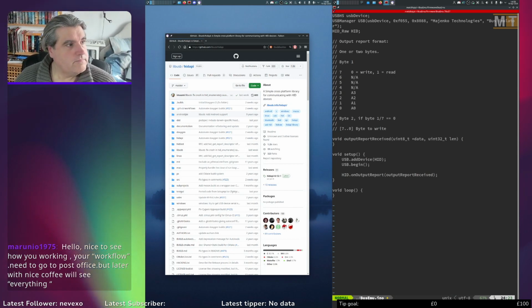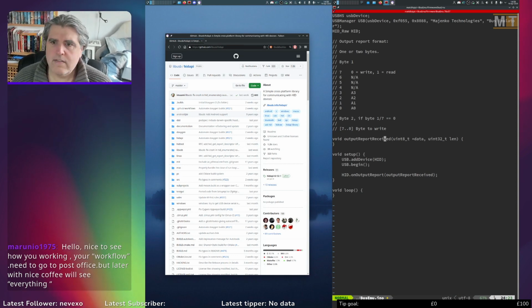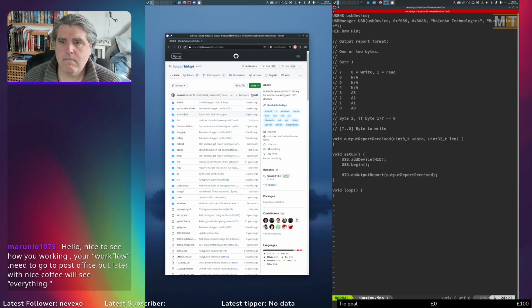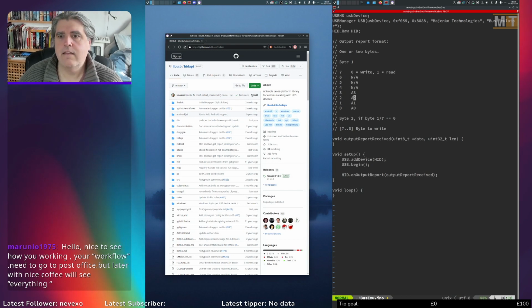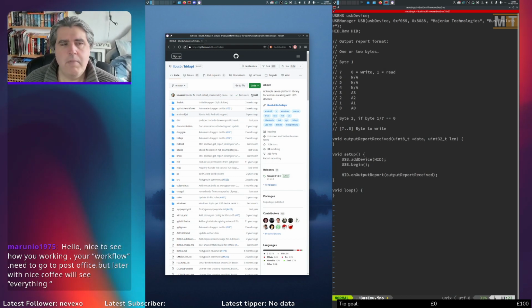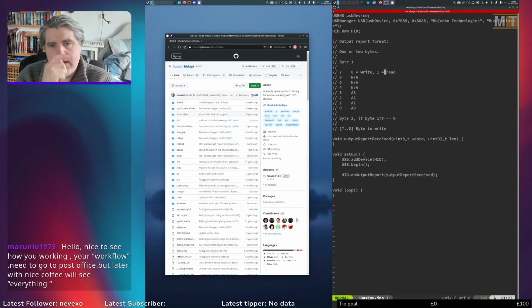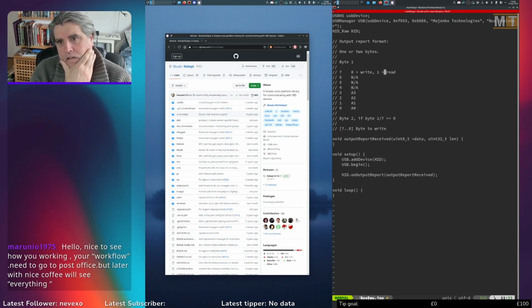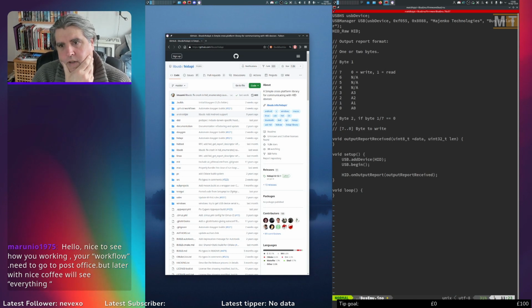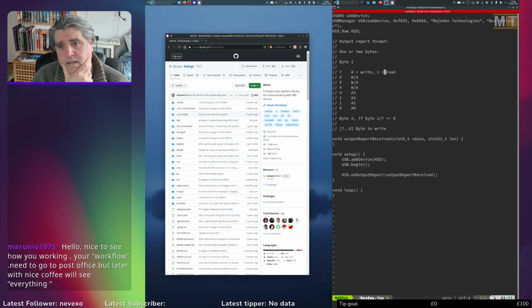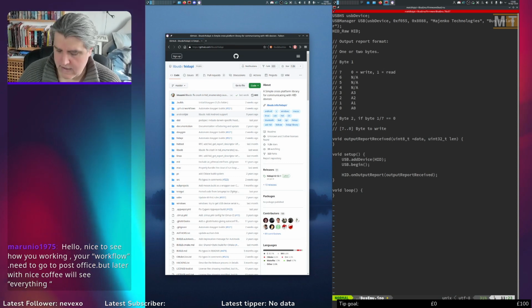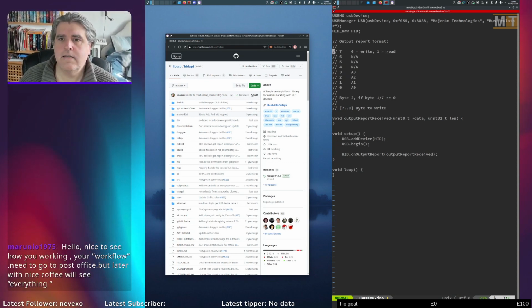Okay, so although actually, do I need the top bit there, do I? Thinking about it, because if it's a read operation, it's a 1-byte packet. The write operation is a 2-byte packet. So I don't need that because I can just look at the length of the packet to know what kind of request it is.